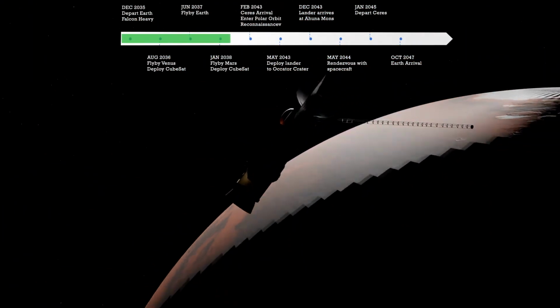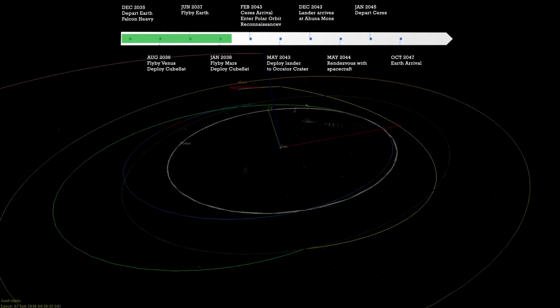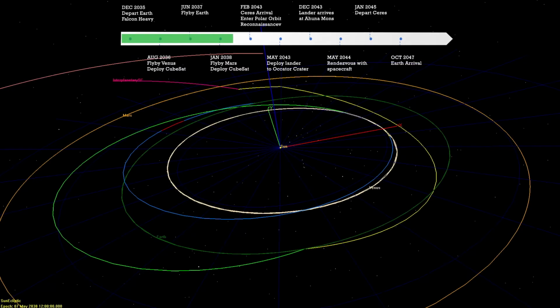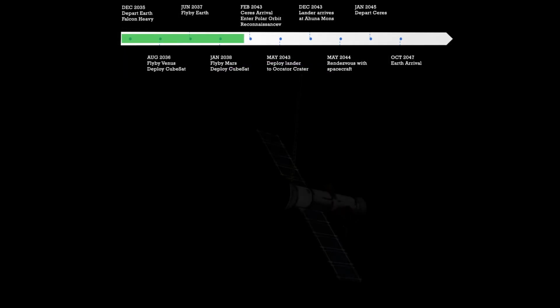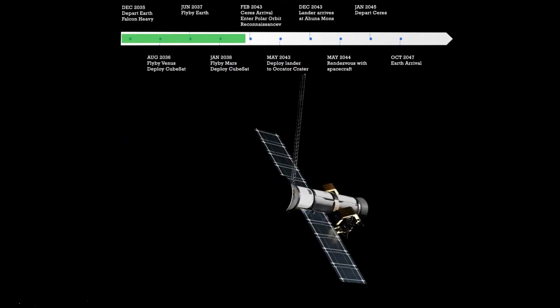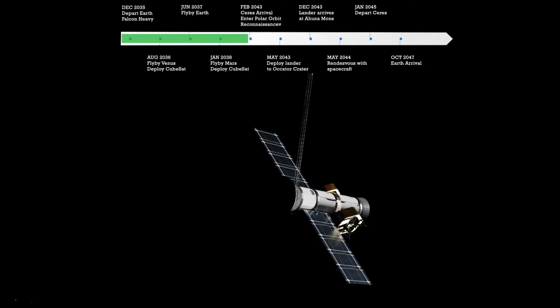The Mars-powered flyby changes our heliocentric energy and deflects the resulting trajectory into the plane of Ceres, reducing the delta V required to capture. Now on the correct orbital plane, the Rocinante will coast in interplanetary space for just under 2,000 days until it arrives at Ceres. Along the way, there will be 2 low-thrust trajectory correction burns to match Ceres' orbit. One final 124 meter per second maneuver with the Super Draco thrusters captures the Rocinante into the orbit of Ceres.